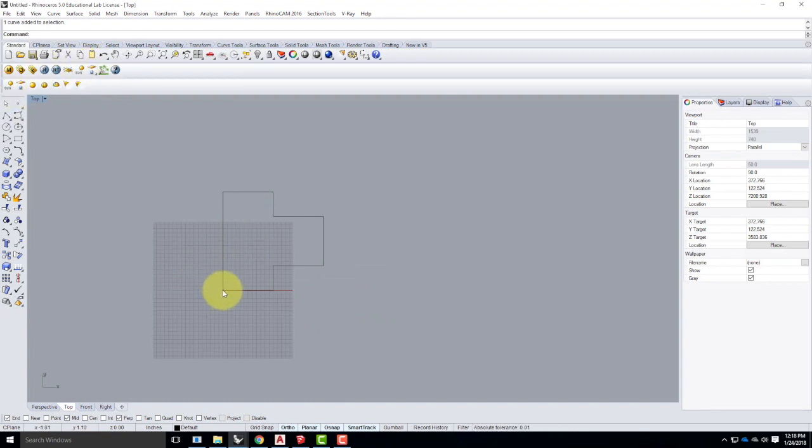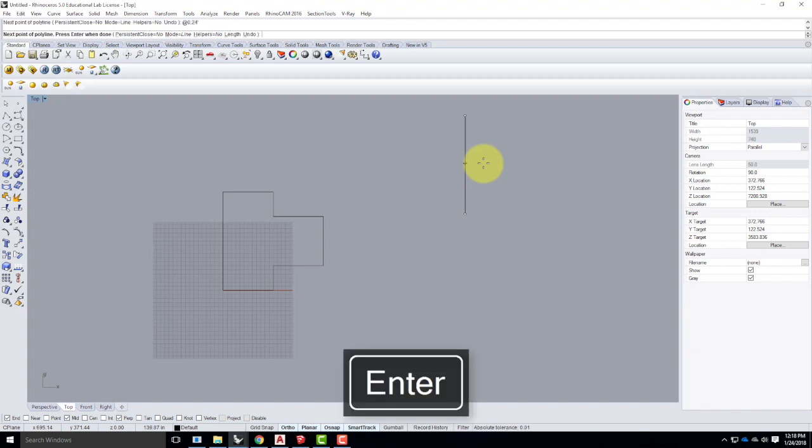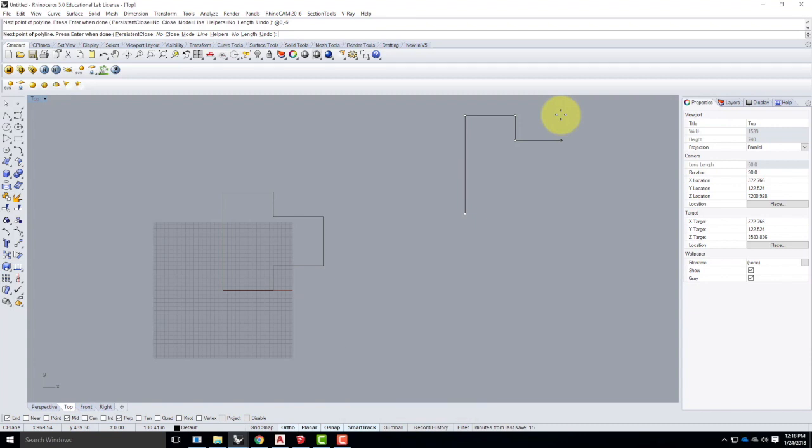If I didn't start at point 0, 0, it would be a lot harder to come up with these absolute coordinates. So if I started way out here, for example, not at point 0, 0, the relative coordinates would be more important. So I could say maybe at 0, 24 feet, at 12 feet, 0, at 0, negative 6 feet. You guys get the idea. This is still an awful lot of math to keep track of, the coordinates and which way am I going and whatever.